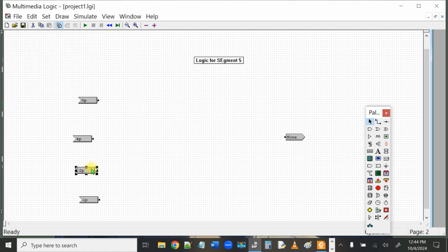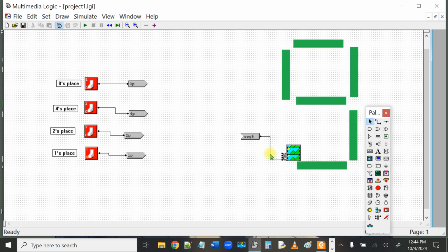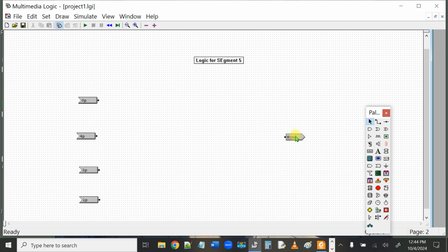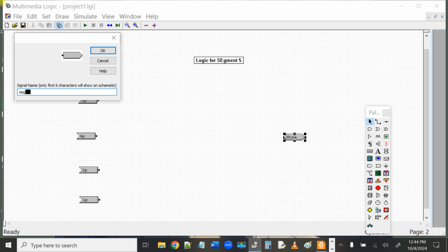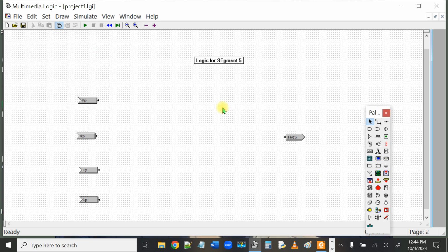Okay, I'm going to straighten these up a little bit. And I think, yes, my receiver back on the front page is seg 5. So I need a sender from all the digital logic I'm about to drop here. I need this to go to seg 5. Okay, now some of this is mechanical, and this is the part we can do without looking. Well, I got to look at the SOP a little bit to see how many AND gates I need. I need 1, 2, 3, 4.